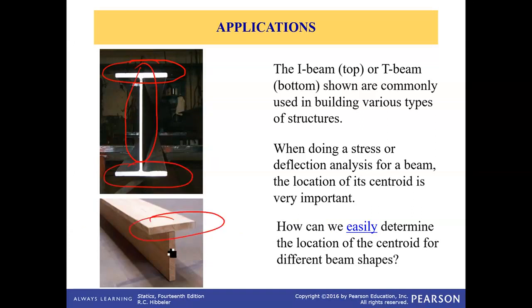This is made up of two shapes, horizontal and vertical rectangles. So in composite bodies, we simplify the shape using standard shapes, then calculate the centroid for each one of these shapes individually using the overall coordinate system, and then apply simple arithmetic to get the centroid of this entire shape or composite body.